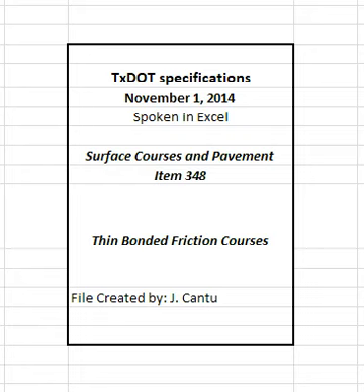Table 2. Gradation requirements for fine aggregate. Sieve size and percent passing by weight or volume. Sieve size 3/8 with 100% passing. Sieve size number 8 with 70 to 100% passing. Sieve size number 200 with 0 to 30% passing.